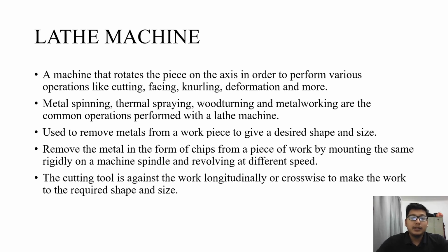It removes the metal in the form of chips from a piece of work by mounting the same rigidly on a machine spindle and revolving it at different speeds. The cutting tool is fed against the work longitudinally or crosswise to make the work the required shape and size.